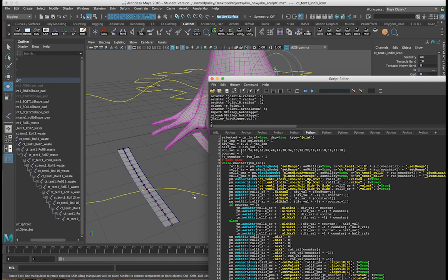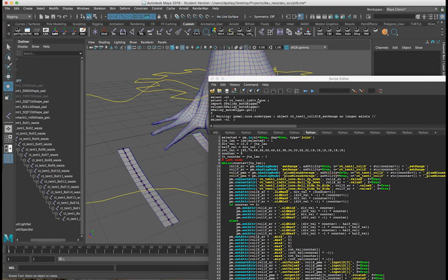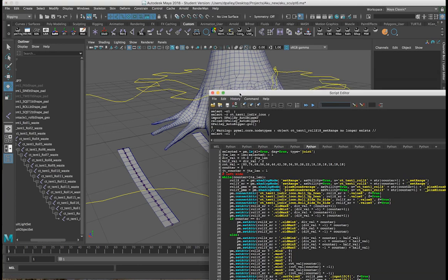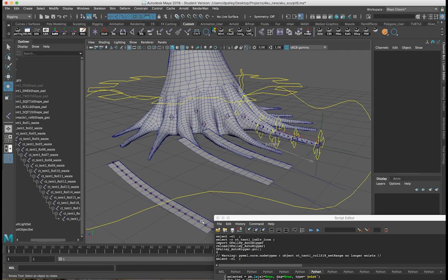So what I did here is adjusted it a little bit. We still use set range nodes, but instead of activating a blend shape with the set range node, we would activate the rotation of each joint here. So as the attribute increases, it will start to activate the rotation of every single joint.